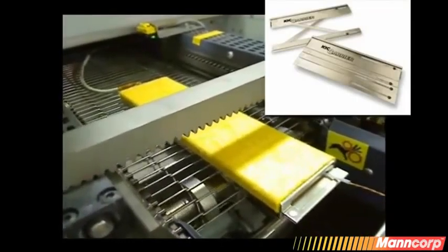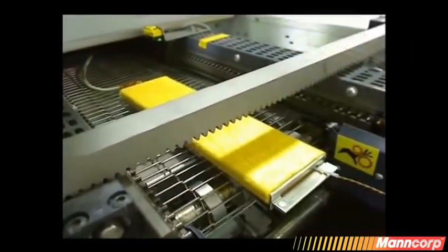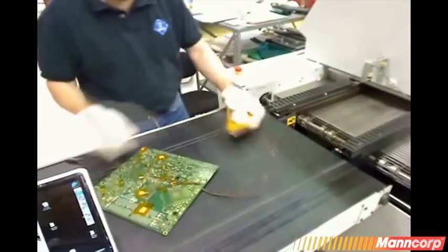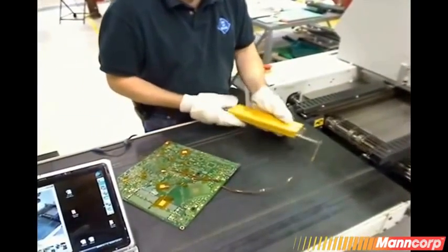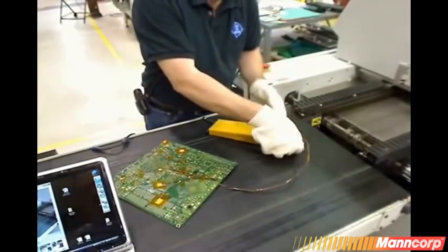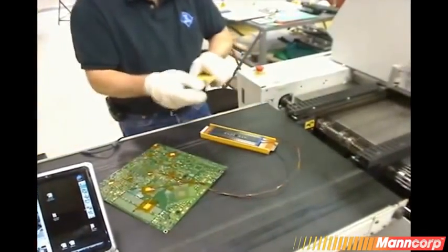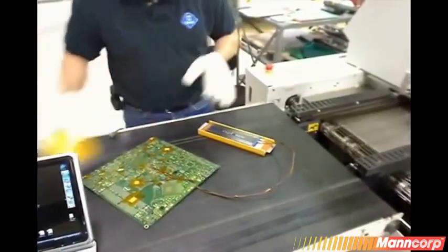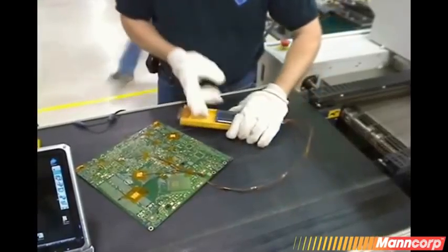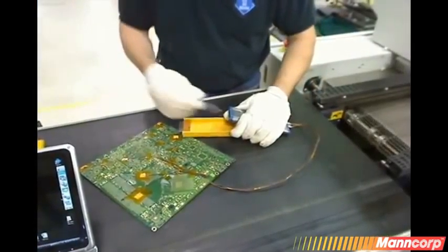In this example, the profiler is loaded into the oven by hand directly onto the belt conveyor. If your oven does not have a belt, a common method is to use a scrap board or an adjustable carrier. If you are using an RF profiler, data will begin to populate your profile graph immediately. Or you can wait for the unit to exit and connect a data log cable to your unit. Some units, such as the one pictured here, have a special shielding allowing you to handle the unit fairly quickly even when exiting a lead-free process.